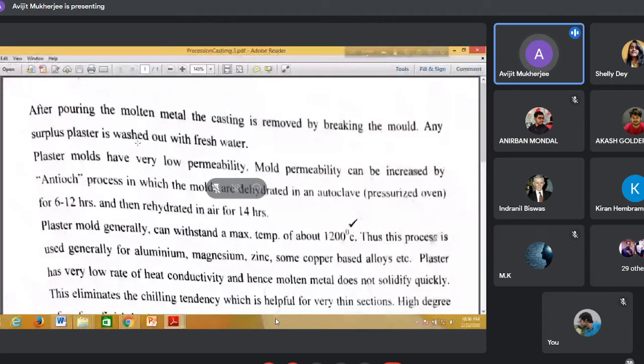The problem of plaster of Paris is that it is a very fine, powdery mass. But I must have the property of the molding material known as porosity or permeability, through which the dissolved gases may escape.